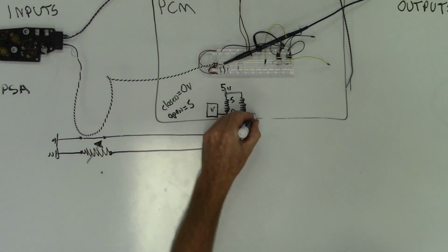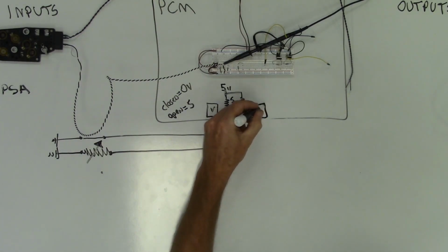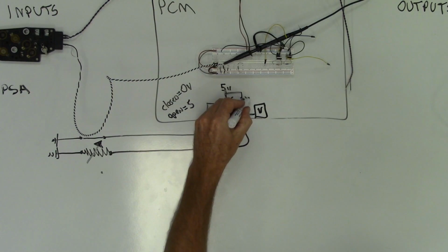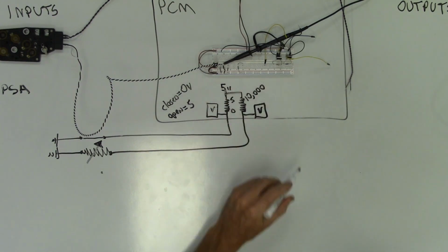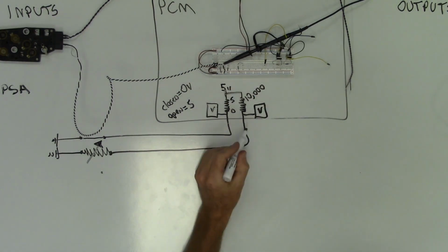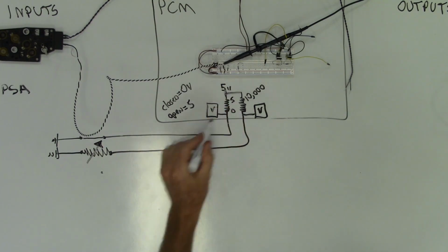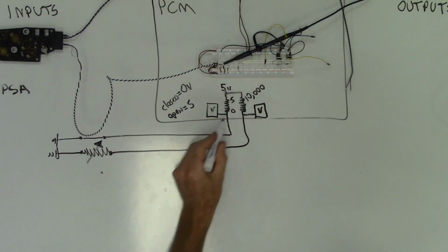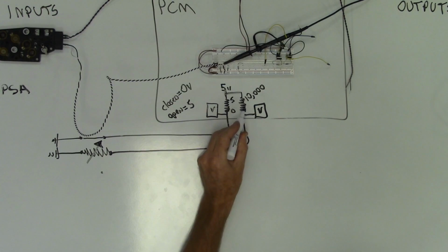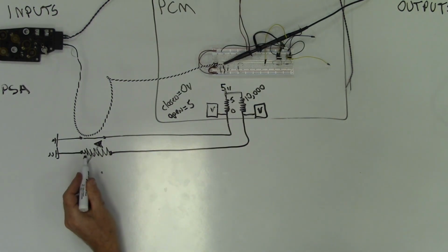And they're still going to look at the voltage on this side right here. This is a fixed resistor, and I've got a 10,000 ohm resistor in there. And that's fixed, that stays the same. So that's basically what we're going to be doing, sharing the voltage drop. It's a series circuit, and this is always 10,000 ohms, and this is going to vary. It might be 20,000 ohms to start, and then the warmer it gets, it might drop down to 1,000 ohms.